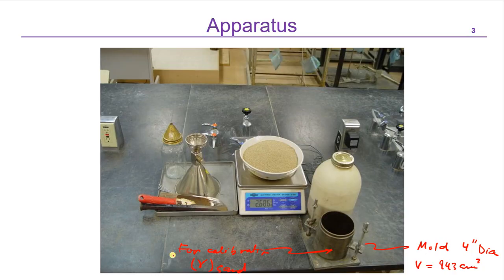What is the test? We excavate a hole in the compacted layer. This hole should go up to the thickness of the layer, or a maximum of 6 inches, whatever is feasible. The soil has to be removed from here.